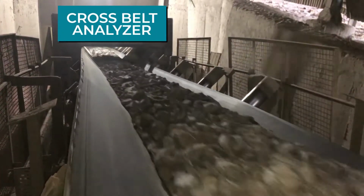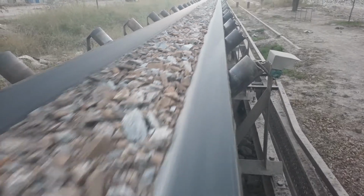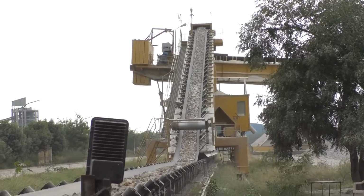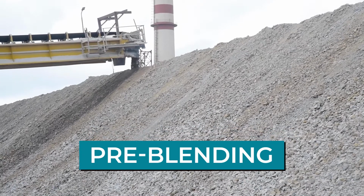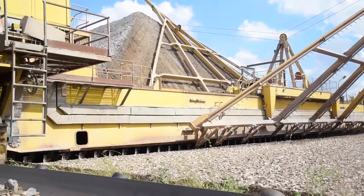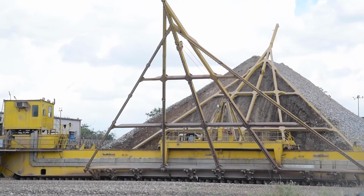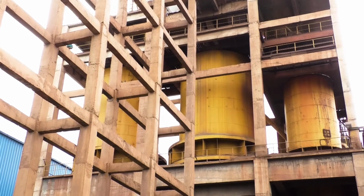The cross-belt analyzer provides minute-wise elemental analysis of crushed limestone with Californium 252 prompt gamma neutron activation analysis technology for online quality of limestone. Pre-blending. Pre-blending equipment, stacker and reclaimer are installed to get constant quality of raw material. With the help of the reclaimer, the longitudinal pile is reclaimed vertically and the material is conveyed to the blending hoppers.